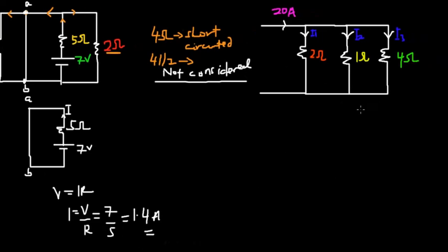From here we could notice that we don't have any short circuit or any of that sort. So we have a certain 2 ohm, 1 ohm, and then 4 ohm. Now from here you could notice that 1 ohm and then 4 ohm are in parallel, because when you traverse through the 1 ohm and 4 ohm, there is no other element.